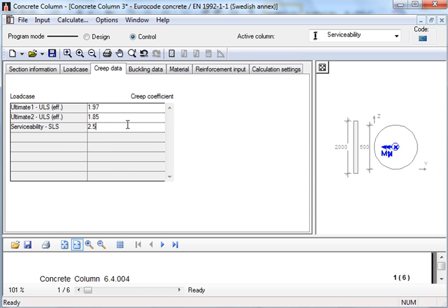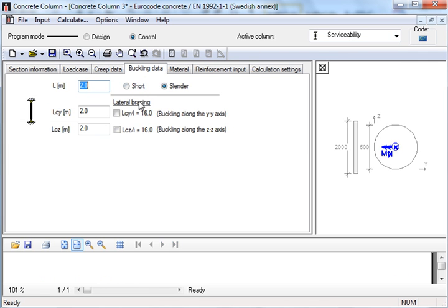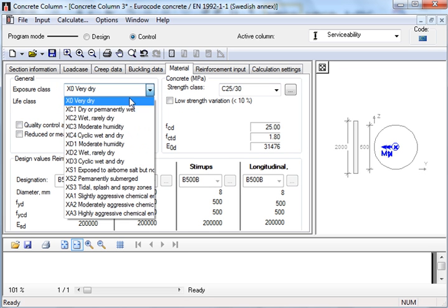As the linked mode is terminated, the new load case does not inherit properties automatically. We could of course select link load cases again, but it's important to first activate one of the ULS cases, as otherwise they will inherit properties from the now active SLS load case that still contains the default values concerning buckling length and materials. We choose the option to define values for the SLS load case and specify buckling length as 6 meter. And the material properties as before.